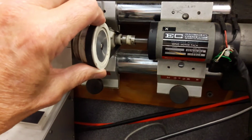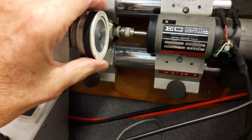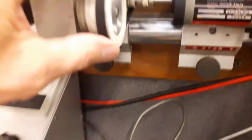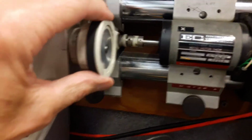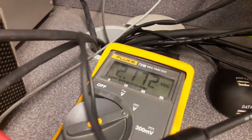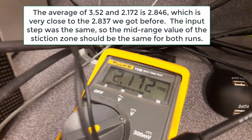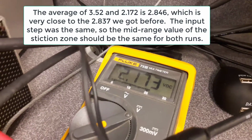But what you would do now, like I said before, is go back here and turn this in one direction until it fights back, record that value, turn it in the other direction until it fights back, record that value, and then the average of those two values is the midpoint of the stiction zone. And if you had no stiction, that mid value is where it would wind up.